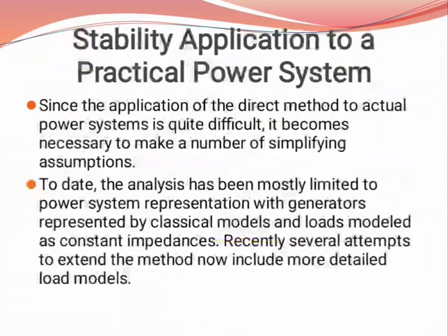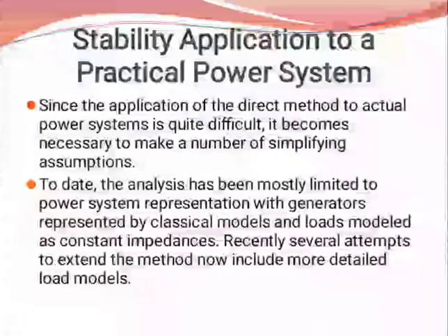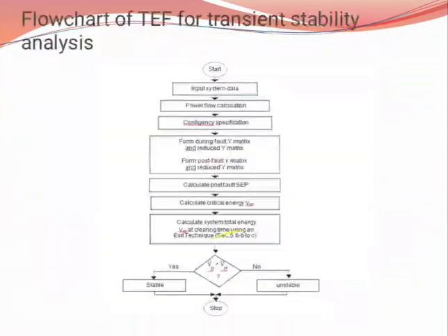Then let us study the stability application to a practical power system. Since the application of the direct methods to the actual power system is very difficult, it becomes necessary to make a number of simplifying assumptions. Up to date, the analysis has been mostly limited to power system representation with the generators represented by classical models, and loads modeled as constant impedances. Recently, several attempts have been made to extend the method, including more detailed load models as explained already.